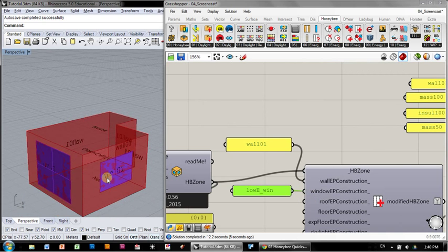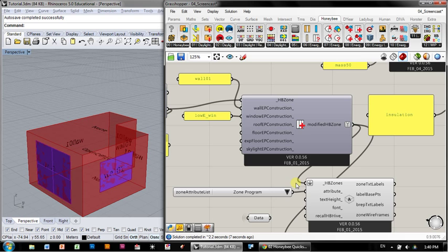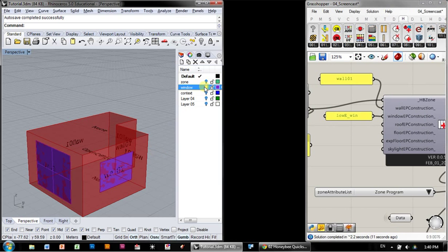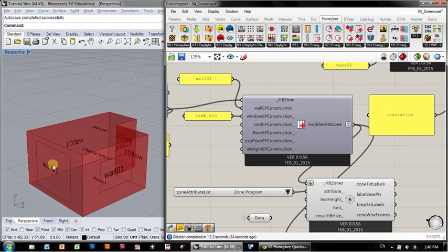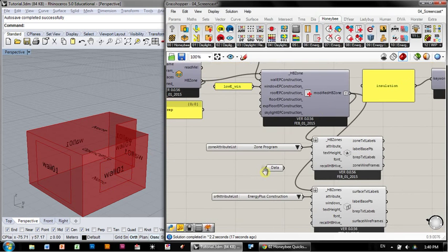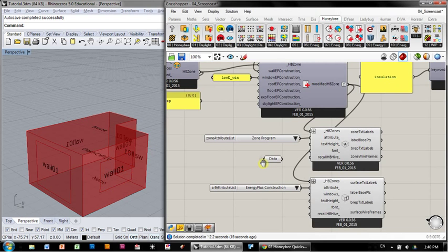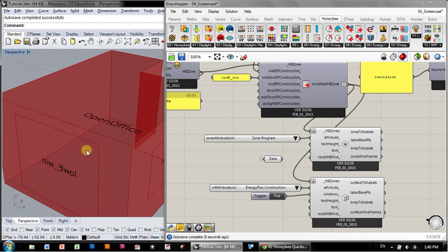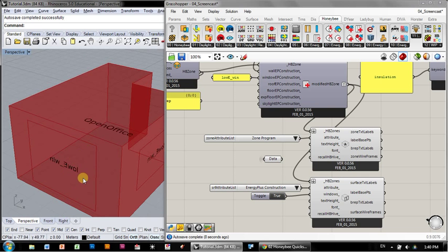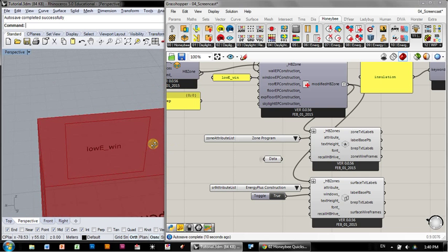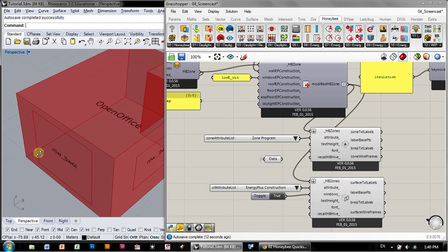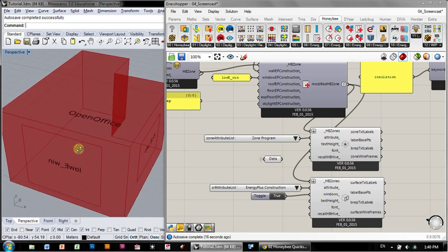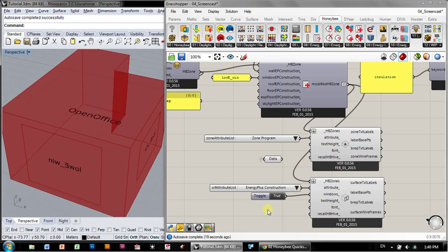Now right now it's set to wall 01. To change that, actually, do I have the windows on? Yes, I do. Aha. So it's seeing the wall, and instead I would like to see the window. In order to do that, I think we need to plug in a boolean here, and you can see the windows. It looks like these windows, the surface normals, are backwards, which is why this is reading backwards. Now you can see it from the other side, Loisos window. But I don't think that matters. This seems to run okay with it backwards, just like that.